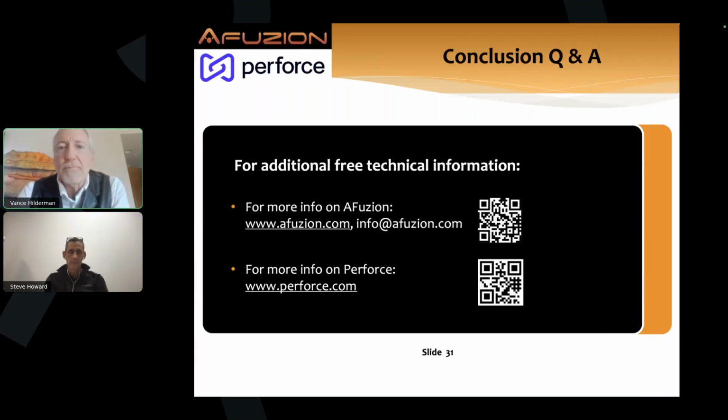There are behaviors that are not fully assessed. Without doing a code review, data flow, control flow, coupling analysis, and really MCDC coverage down to DAL A, level A, criticality level, the highest level, 10 to minus 9 on part 25 large aircraft, you don't really know for certain, okay? So to be safe, you should simply certify the software, but almost no one does. Interesting. And there's no plans to change that in DO-178D for the future. So I'll probably be retired by then. Next question. Let's move along here, okay?